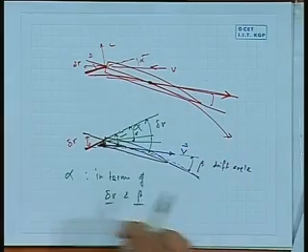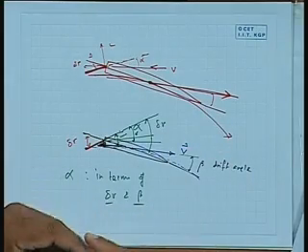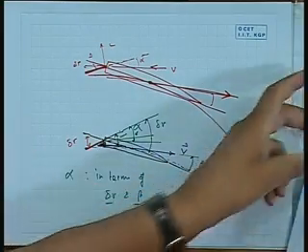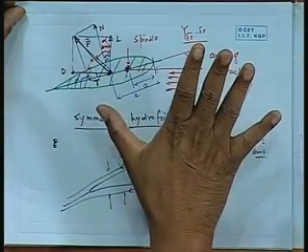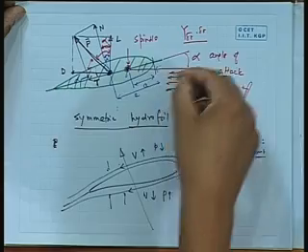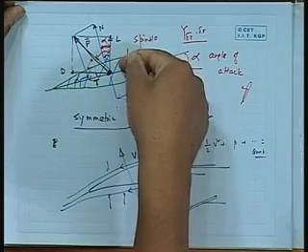You can express that in terms of delta and beta. So, you know now, for a section, what my effective angle of attack is in terms of the rudder angle delta r and the drift angle beta. So, you will know the angle of attack.